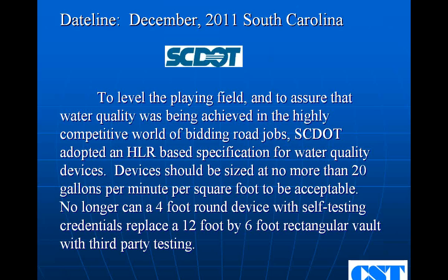Now this new protocol is being, people are applying for approval under it now, but they adopted an HLR-based specification. They say a device should be sized at no more than 20 gallons per minute per square foot. They're a little tougher than I am to be acceptable. They will accept it, I think, up to 26 or 28 if you can advocate for a particular reason. It's a super clean area, whatever, another BMP downstream.